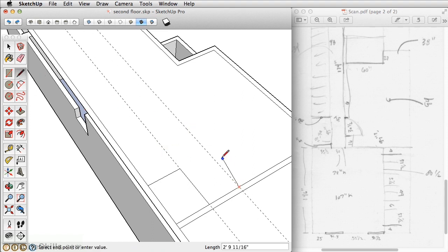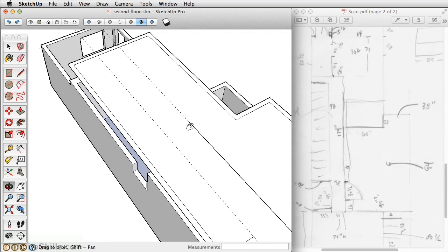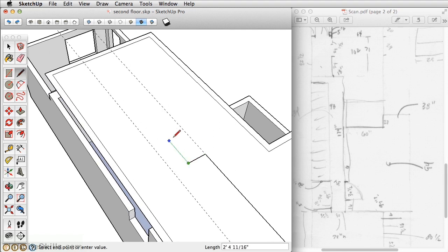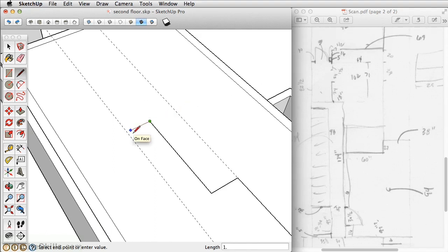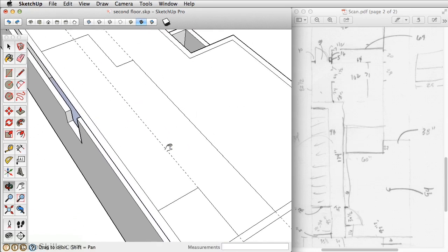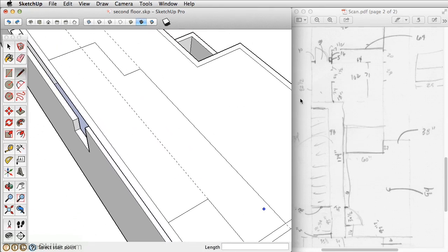Now take the line tool, draw 16 inches, then the doorway is 30.5, and then it's 174 inches to this wall right here. Then it's 18 inches, 34 inches, 24-inch door. It's a really narrow door to the bathroom. Then it's a really narrow trim to the other door here. So it's 1.5 inches. Then you have 1.5 inches this way. Then a 30-inch door, and then the remaining wall here. Our opening length here is 82.5 inches.